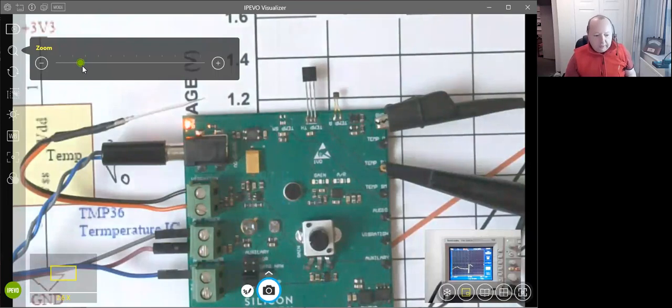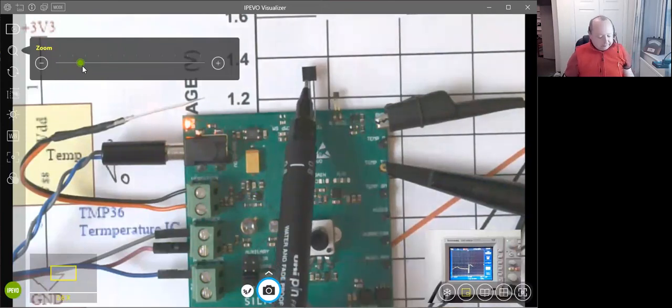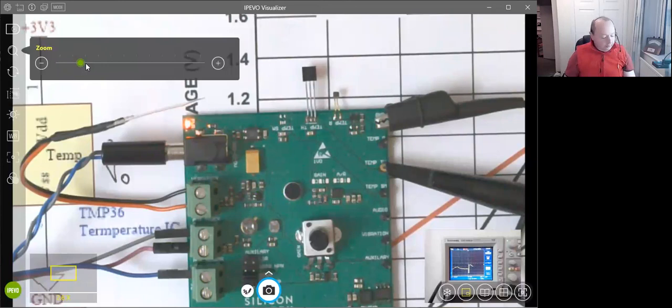And I've also found with temperature sensors that if you try and measure the ambient temperature with a surface mount device on the PCB, because there's heat in the PCB, it will affect the temperature of the reading. So if you want to measure the environment, I find you're much better having the device on legs. If you want to go really fast sensitive, of course, we use a thermocouple, which we've not got here today.